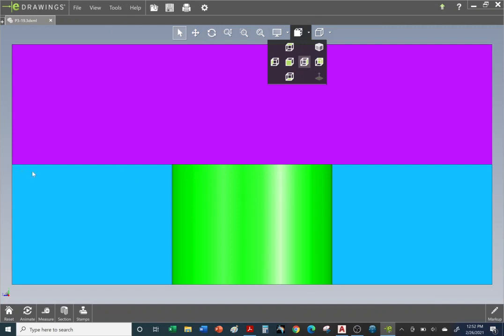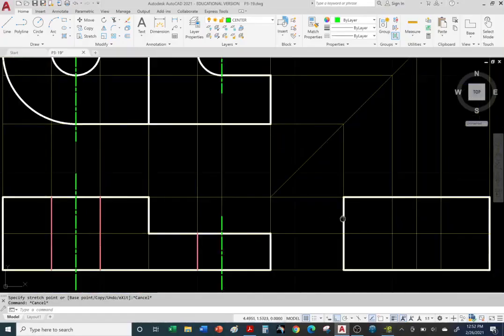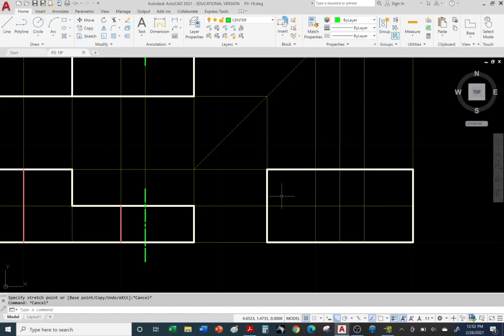All right, so we need to draw this object line and these object lines, right? We can see them, so we're going to draw them as solid object lines. All right, so let's complete the right side view. Let's go to visible white object layer. Use the line command. And again, from every corner, let me turn on object snap. You can track across. So there it is. There's that corner. And click. And click. There it is. Right click enter to exit.